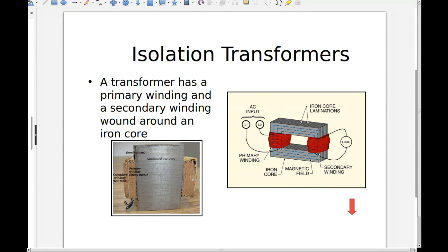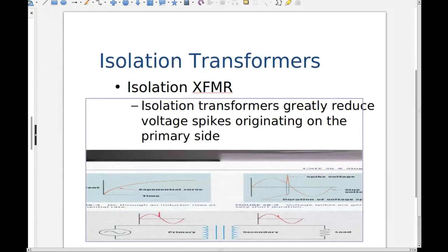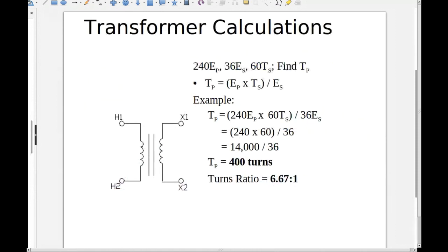So you think about thousands of miles of that, lightning is going to hit those sometimes. But we get electrical isolation from that because of all the transformers it has to go through. We do see spikes in the voltages due to lightning hitting it, but we don't have a direct electrical connection.